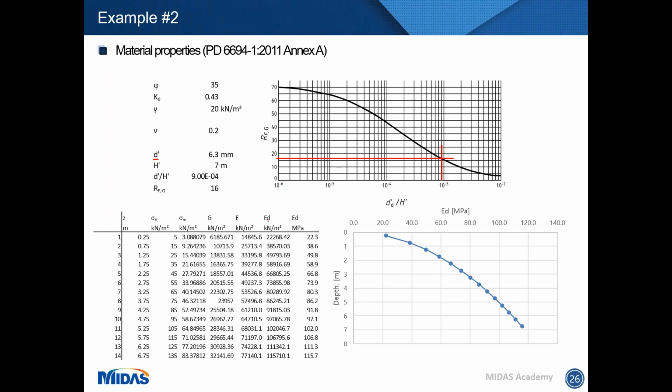I'm showing you the whole calculation, but basically what you're after is this Young's modulus, which increases with the depth. And it doesn't increase linearly, it increases slightly exponentially. Obviously, these values depend on the value D prime, which gives us this factor here, which basically determines the value of the elastic modulus, but we don't know for sure that's the value that we are going to get from our model.